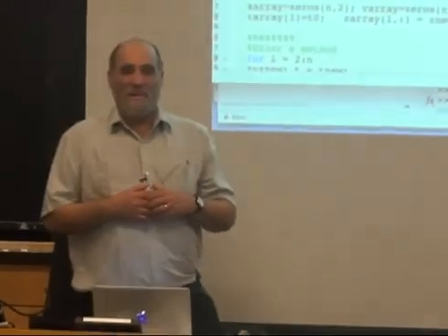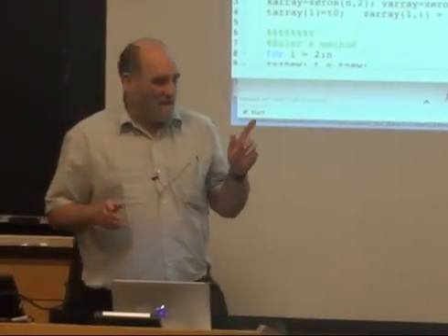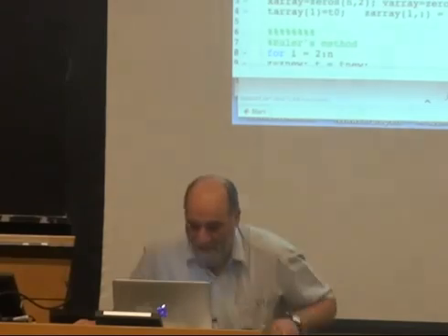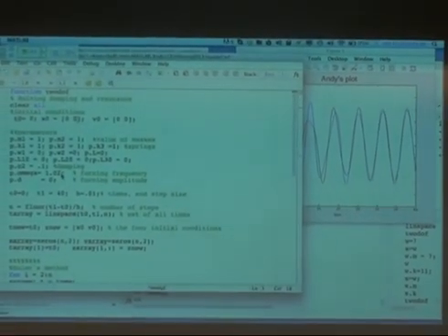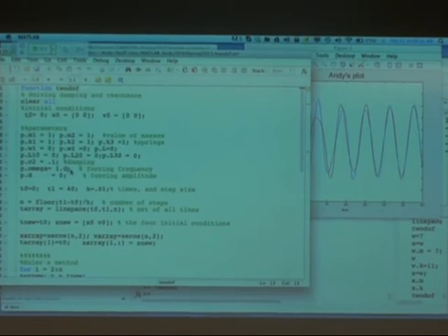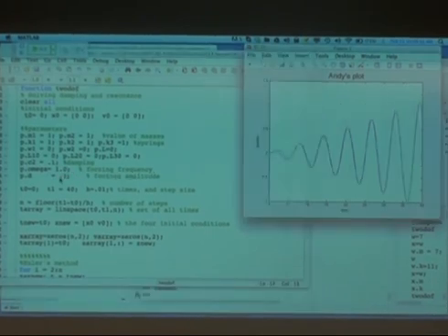Okay, is there some feature of the solutions or the setup that you would have questions about? So the claim is, if I force that at just the right frequency, and I start it at, say, 0 and 0, what would be just the right frequency? In this case, it turns out 1 is one of the just right frequencies. I put in just a small displacement here, and then I run this thing, I get resonance. So even though this has 2 degrees of freedom, I get a resonance by forcing it at the right frequency. There's another cool frequency I can set this to, which is about.